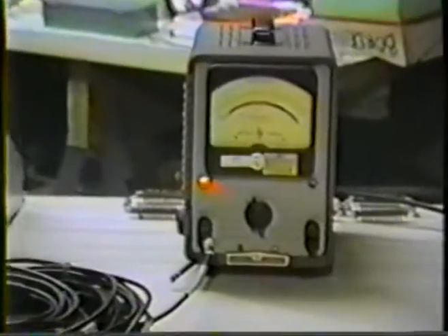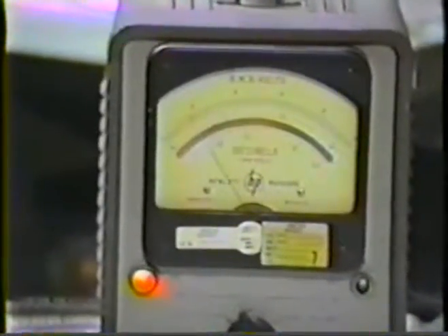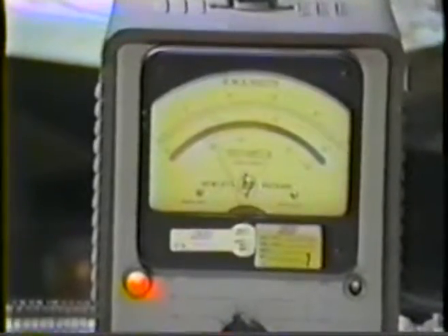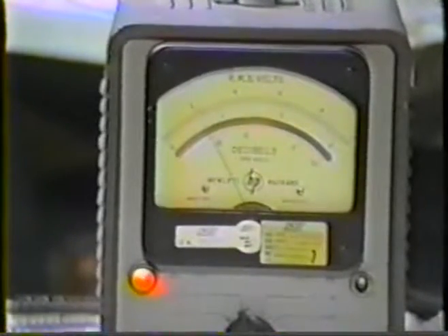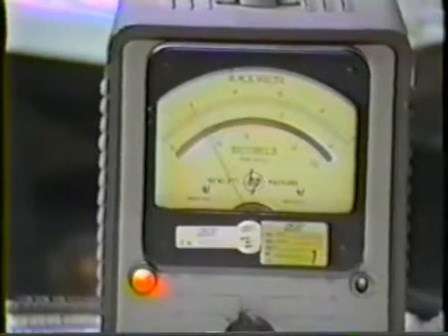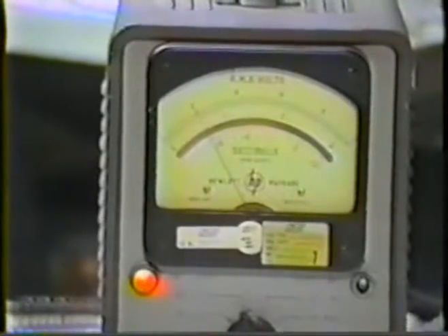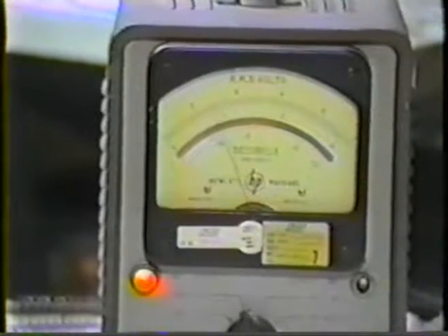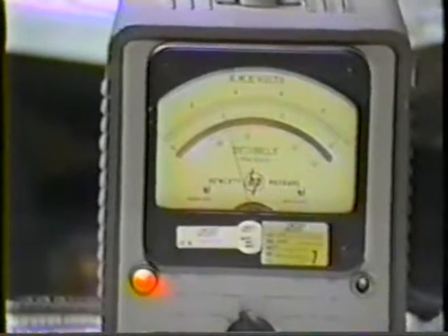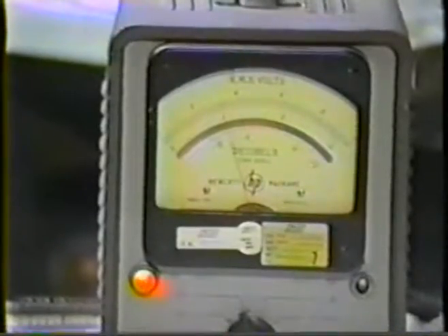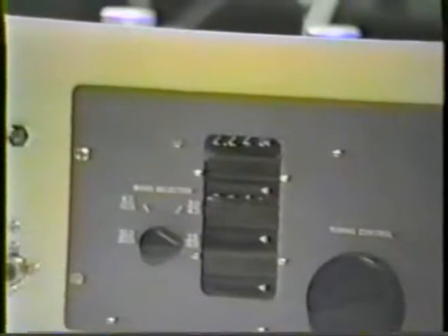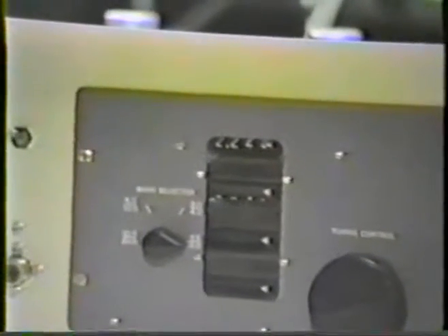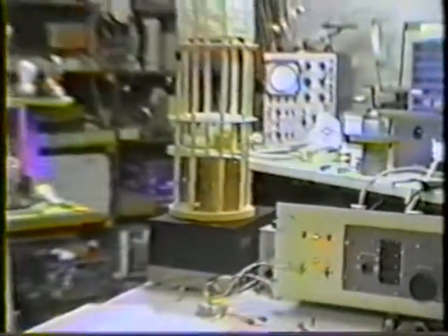Now, as you can see on the voltmeter here, we have a definite peak. So I'm sweeping the oscillator. If we go to roughly our half voltage points, we find we have a bandwidth of about a few hundred kilocycles, roughly. And it peaks out at a frequency of almost precisely 2,220 kilocycles. So what we'll do next is plug this into our equations and determine the speed at which our impulses propagate on the coaxial cable.